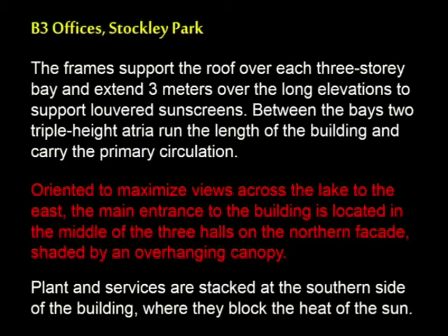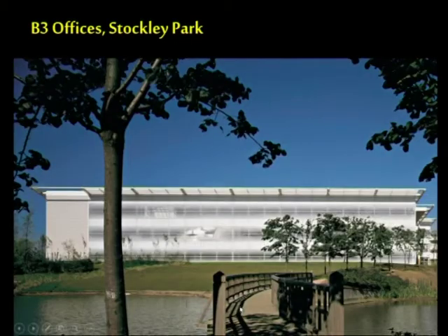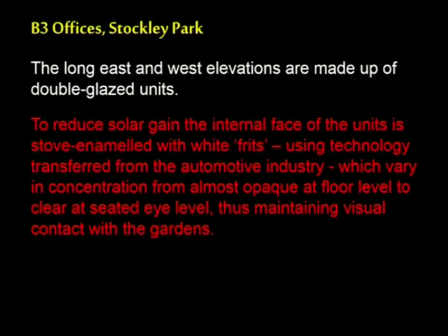Plant and services are stacked at the southern side of the building, where they block the heat of the sun. On the front is the lake that they were talking about. The long east and west elevations are made up of double glazed units. To reduce solar gain, the internal face of the units is stove enamelled with white frit, using technology transferred from the automotive industry, which varies in concentration from almost opaque at the floor level to clear at the seated eye level, thus maintaining visual contact with the gardens.